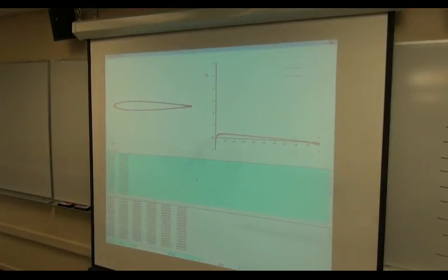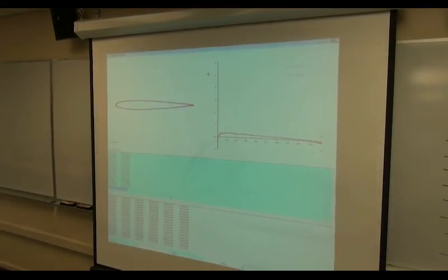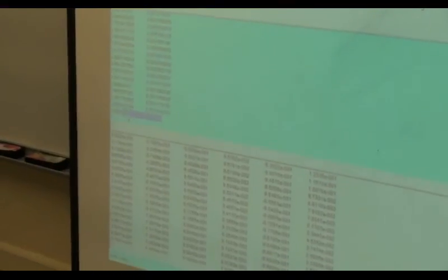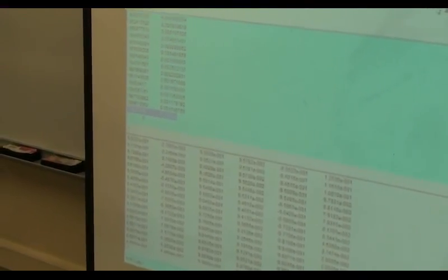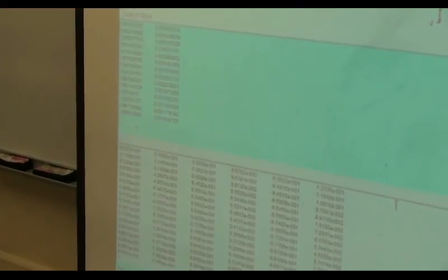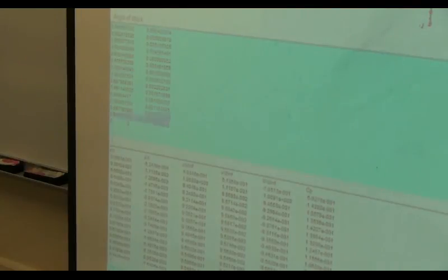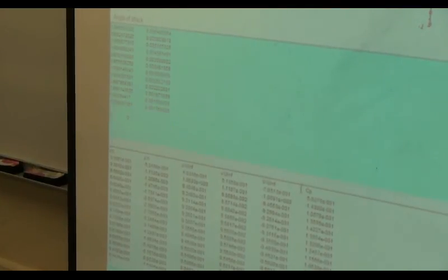Then I'm going to go all the way down right next to the bottom surface, actually top surface, deleting this point. Can you zoom really in to show the numbers? Okay, what I'm doing is I'm going to highlight, looks like right next to the trailing edge. I don't need this data point, so I'm going to remove it. Okay? And let's compute again. Oh, I still have a few more points. I'm going to remove those two.